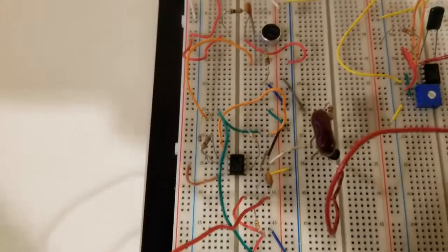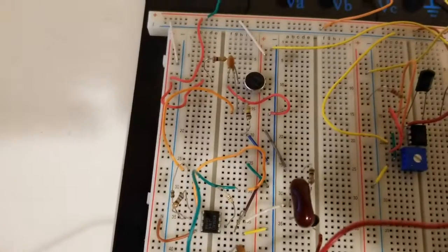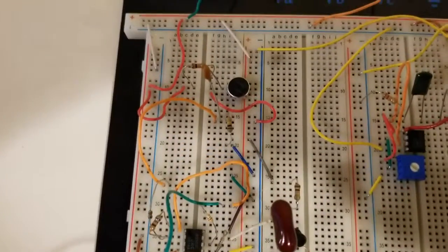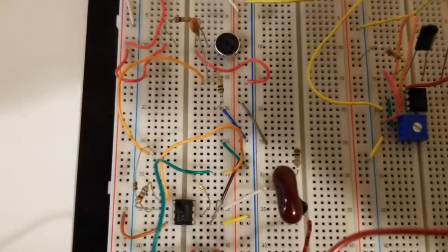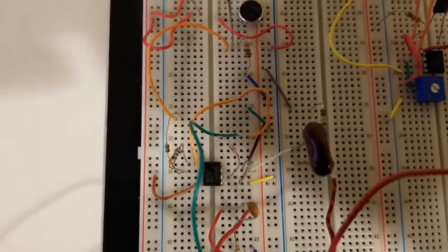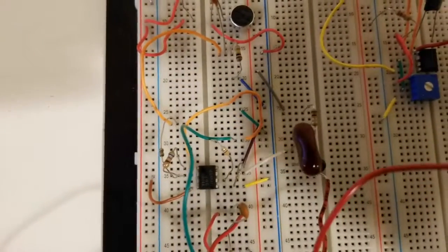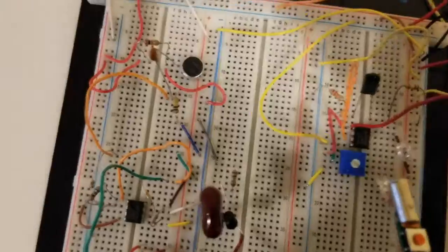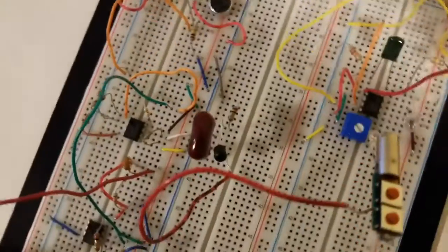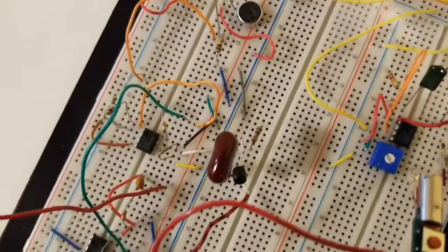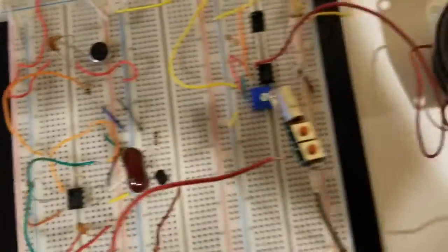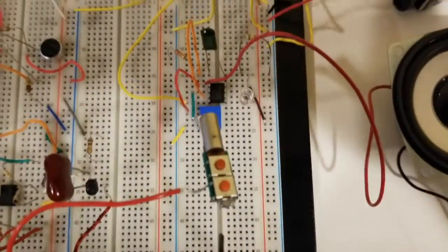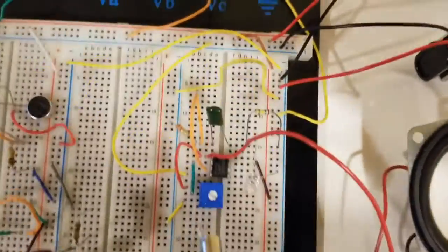Then those signals were amplified, and they were brought via this green wire and this orange wire to the summing op amp, which is over in the middle here. The output of that summing op amp was taken to the middle of the circuit board, with this capacitor and inductor and resistor configuration over here to create the bias T, which is then connected to the laser, which is over here. Now we have the receiver circuit.